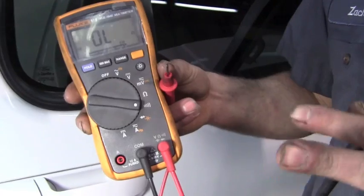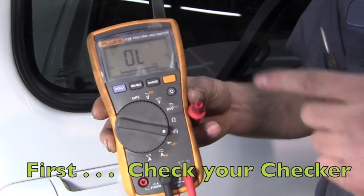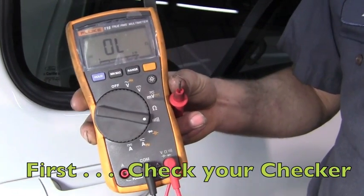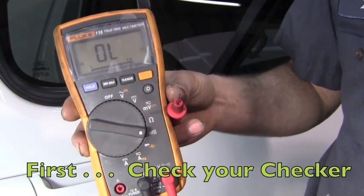Let's go ahead and check our voltmeter and make sure that it's working properly. Now we're showing out of limits here, which means we have an open. So when we place our leads together, it should beep and tell us that we have continuity.